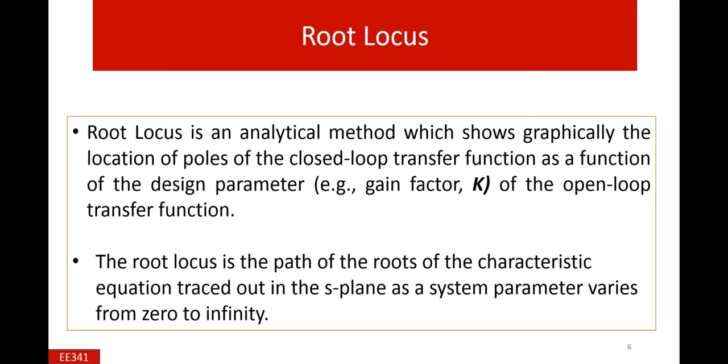A more mathematical and more understandable definition is that it is the path of roots of a characteristic equation in the S plane when the system parameter changes from 0 to infinity. When the open loop transfer function is given, we find the closed loop transfer function, and the denominator of the closed loop transfer function is the characteristic equation.